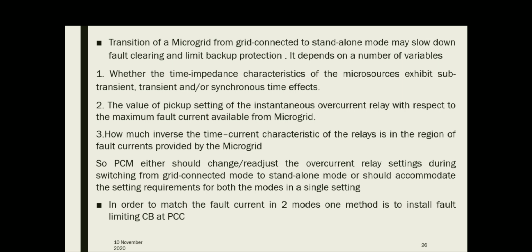This will depend upon a number of situations. First one is whether the time dependence characteristics of the micro sources exhibit subtransient, transient, or synchronous time effects. Second one is the value of the pickup setting of the high set instantaneous overcurrent relay with respect to the maximum fault current available from the microgrid.